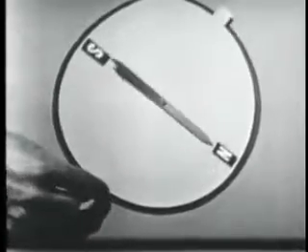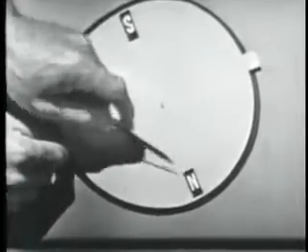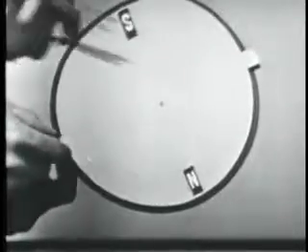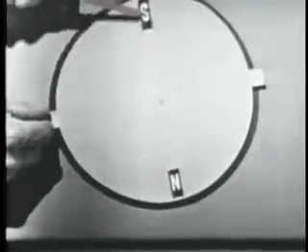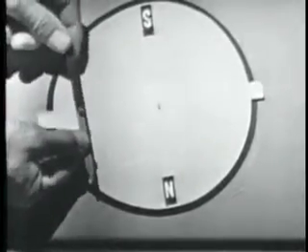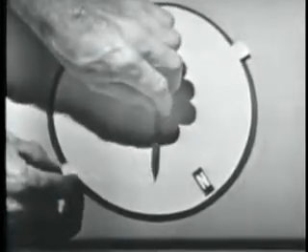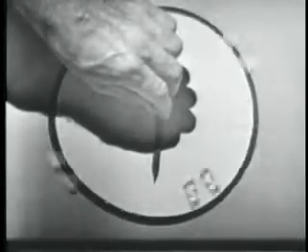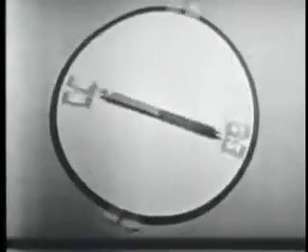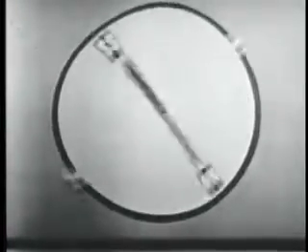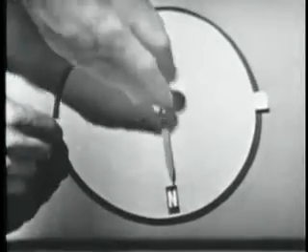Okay, what we have here is a cardboard disc, and it's mounted on a pivot, by the way, so that we can spin it, and we have 2 permanent magnets glued to the disc. Thus, if we spin the disc, we have a rotating magnetic field. Now, the principle we want to show you here is that if we take another magnet, such as this compass needle, and put it on the pivot, so it's free to rotate, and we spin the cardboard disc, we have a rotating magnetic field. Now, you'll notice that the compass needle picks up the rotation of the rotating magnetic field, tries to align with it. Now, this is an extremely important principle.